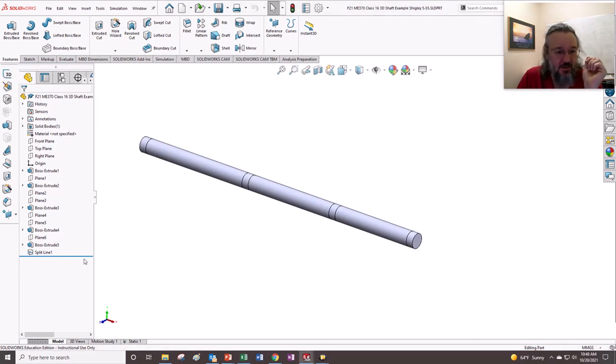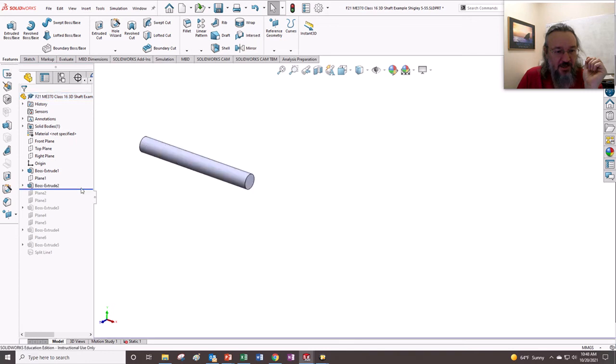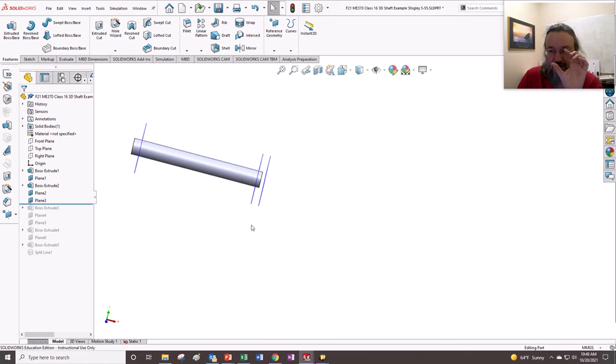So let's see, I'll go back in time and I can show that that's what I did. I started out with 25 millimeters, and then I made a plane, and then I extended this 400 millimeters, and then I added actually two planes. I'll turn the planes on, I'll show you. I added a plane right there, and then I added a plane to either side of this, right? So you can see, and I made it so it's 12.5 to each side of the center of the gear, right?